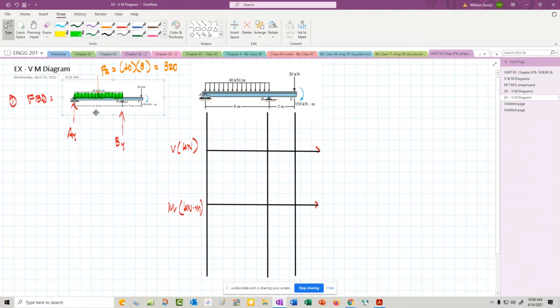All right, free body diagram. If we go through that, find the reactions, free body the entire thing. I would start out by summing the moments about the end, probably. Counterclockwise there. We have minus AY times, what do we have here?